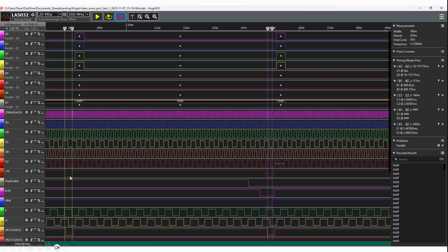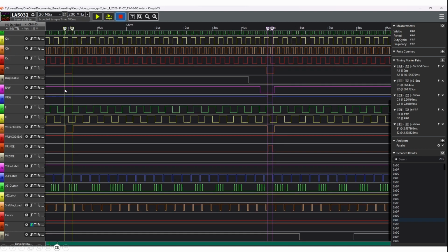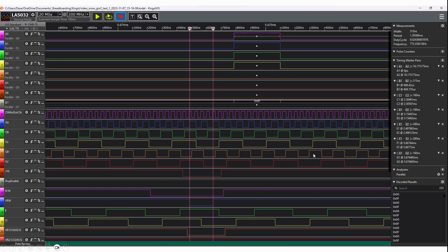And in fact, with drawing the white line, because it reads the RAM first before setting the bits, we've got a read here where we're getting some interference. Then we've got the write here where we've got the Y0 signal and also the video read-write signal. And so what this indicates again is that these are the signals that we need to synchronize with the character latch values, and you can see down the bottom here this is where it's overlapping with the character latch.